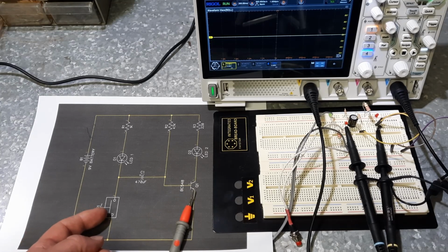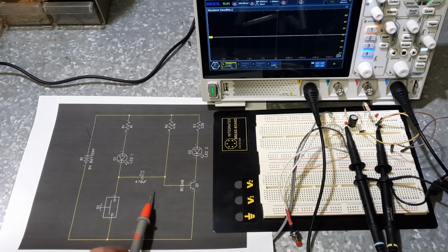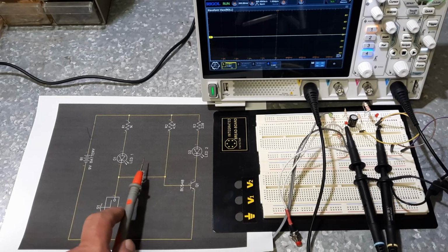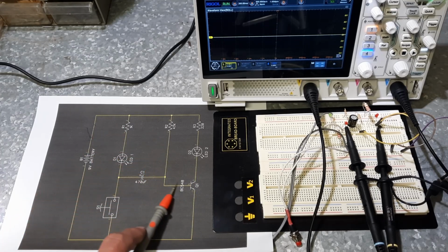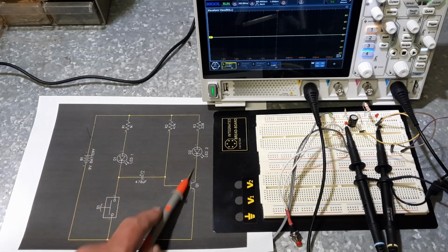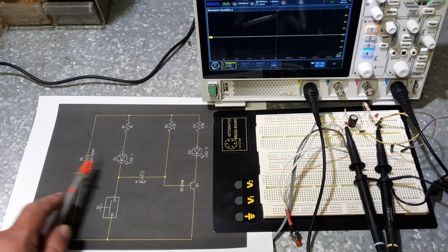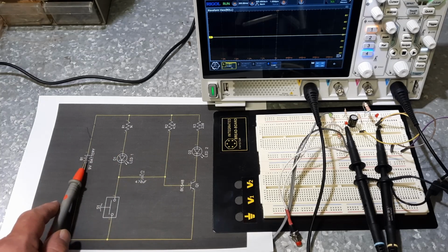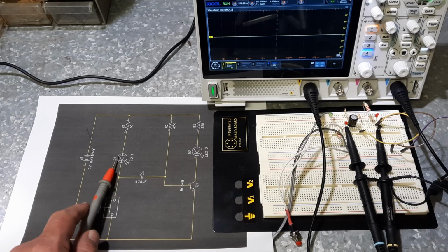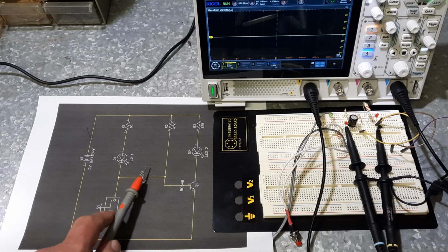So with me holding this, and this having passed through 0 and back up to its 0.7 in the reverse direction, both of these LEDs will still be on, because we're going to have current flowing down here, which will saturate the transistor, current flowing down here, lighting this LED 2, and then we're also going to have current flowing down here, which will be lighting LED 1, and it'll be holding this at a 0.7 of a volt reverse charge.